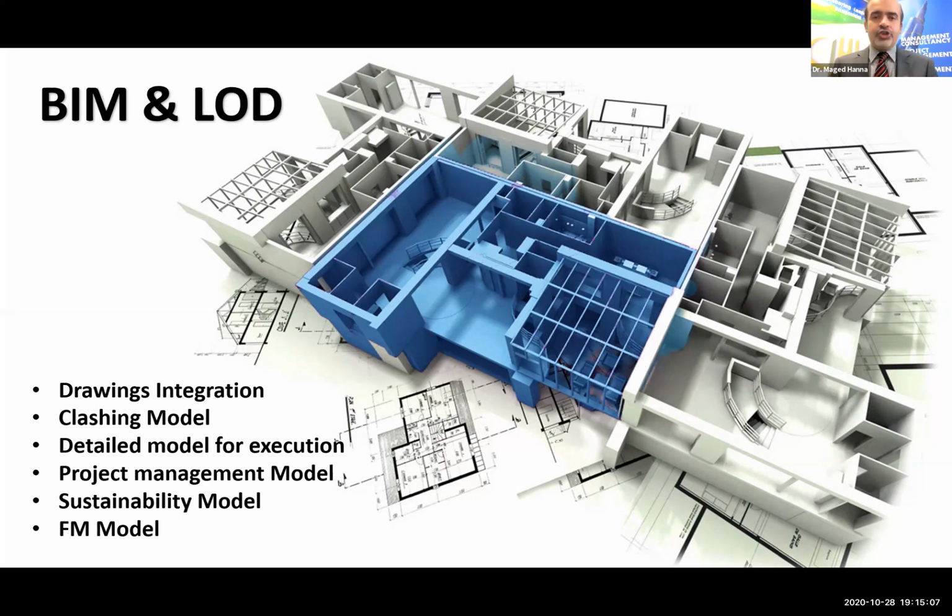But BIM gives us, as a tool, the ease of integrating all the different drawing models in the design with the maximum detail, from LOD 100 to LOD 600, which can reach the furniture, interiors and fit out, moving to LOD 700, which is for FM and maintenance. You need to reintegrate from the beginning. So you really need to think, when you talk about BIM and the models, about level 1, level 2, level 3, or 1D, 2D, 3D, all from approvals till execution.